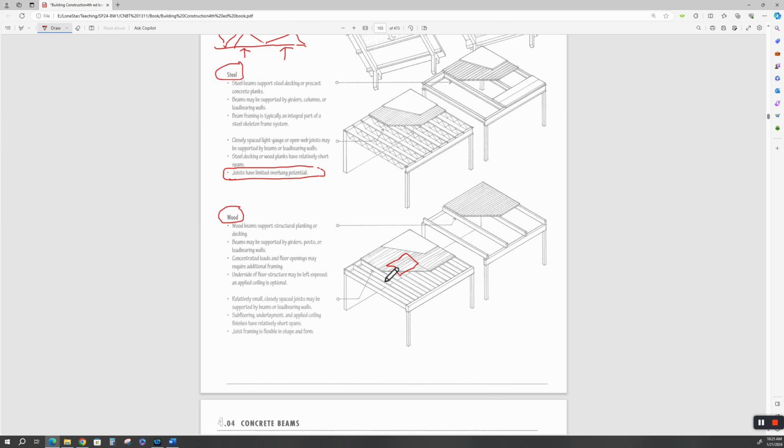Subflooring. That's the underlayment. Now, if this is plywood, we can make this plywood subfloor a diaphragm if we glue and closely screw or do engineering nailing. You and your structural engineer will have to have that conversation. If you don't approach this as a diaphragm, then you're really missing an opportunity to stiffen up your structure and make it lighter.